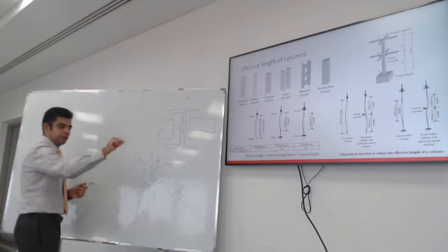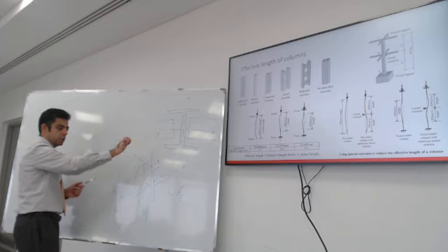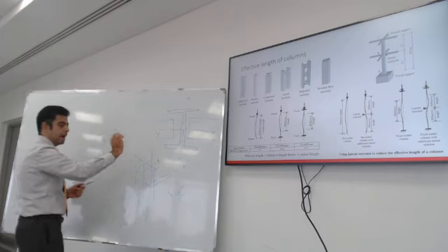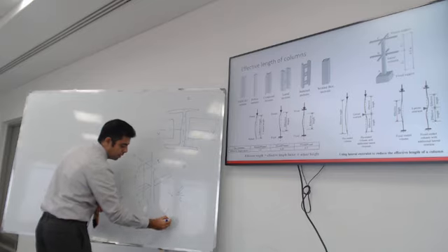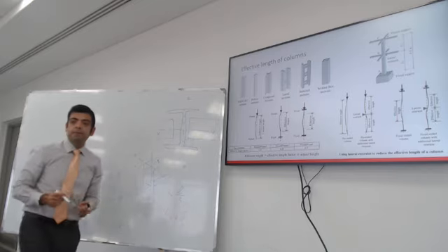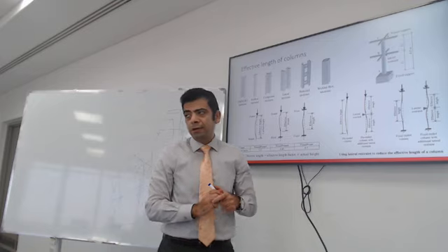Because you put your finger in Z and your other fingers are showing you the buckling about Z. And about Y, the effective length will be about L. Y is the full length. Super important to get this, all right?